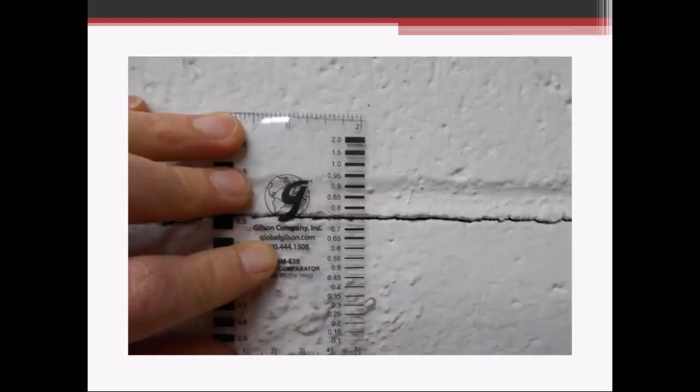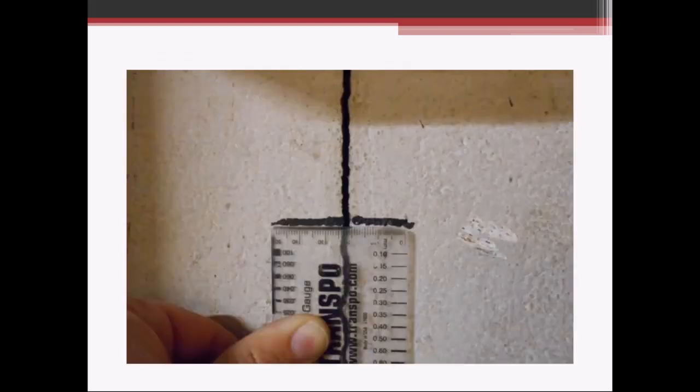Cracks in walls, CMU walls, measure the magnitude. If you can, put one of these crack comparator gauges up there, take a picture of it. And what I like to do is put a line across there so I can go back to that particular location and say, okay, on this date, and a lot of times I'll put my initials and a date on there, on this date, the crack was 3.5 millimeters in width or something like that. These are the kind of things that we certainly want to see documented really well in a condition survey report.